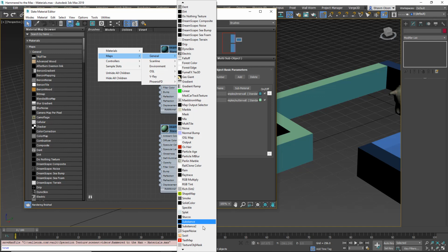Now this is important. There are different versions of the Substance plugin: the one that comes with Max and the one that Algorithmic has updated more recently. There are caveats with both of these. The first issue is, as of this recording, Substance 2, which is the newest version, has many bugs, and I'm going to avoid that one for now. The other caveat is the one that comes pre-installed with Max, Substance. It doesn't load the newest versions of Substance Engine. So you have to pick and choose based off of your needs. Hopefully Algorithmic will update their Substance Map plugin soon, but we're going to use a standard one.